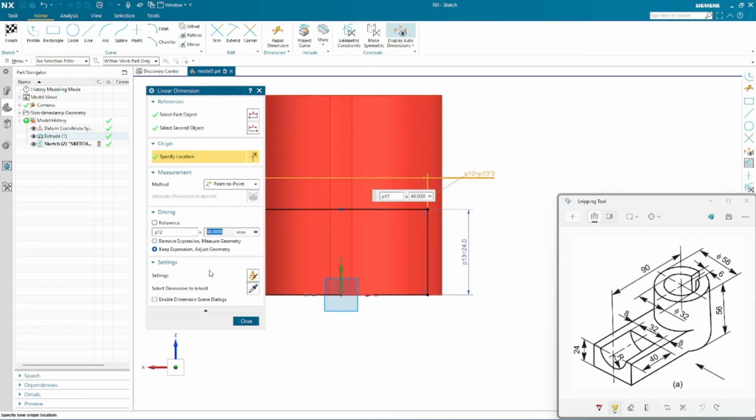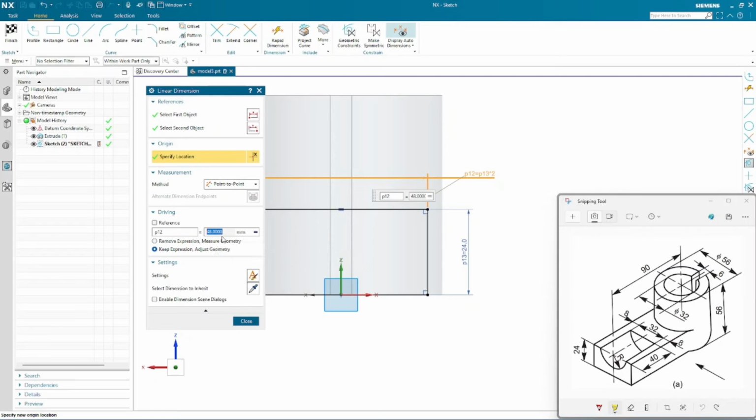Okay, is it the value you can see here, 48? But now you cannot manually change this value. It is grayed out. If you type something, it will not be affected. And if you want to make it constant again, the way you wanted earlier to manually change it, you can just click here and make constant. It will remove the formula.